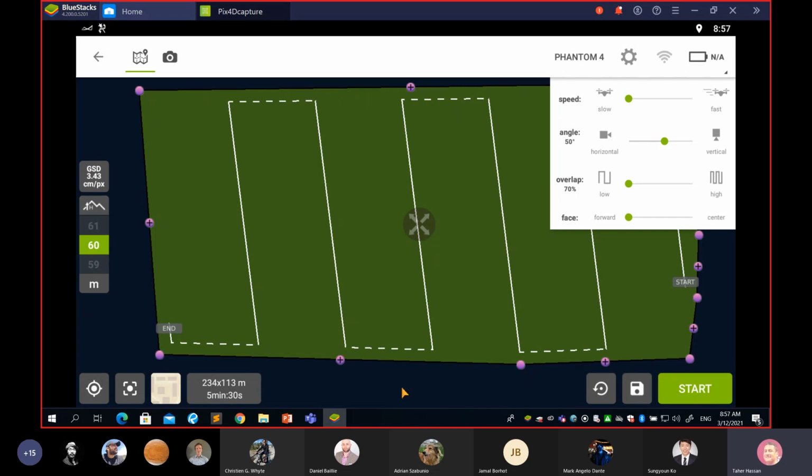And remember, the drone will fly, let's say from somewhere here, will go to the right elevation of 60 meters up, and then turn straight into the first flight line, and proceed along the first flight line and take one image here. After one distance, it will take another image, another image, another image, until here. Then it turns at this angle, and it goes back in a zigzag pattern until it covers the entire area. Once finished, it goes back to where it flew from.